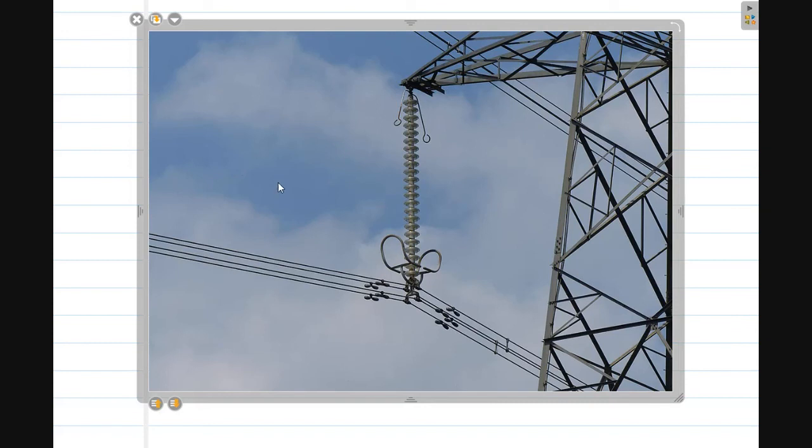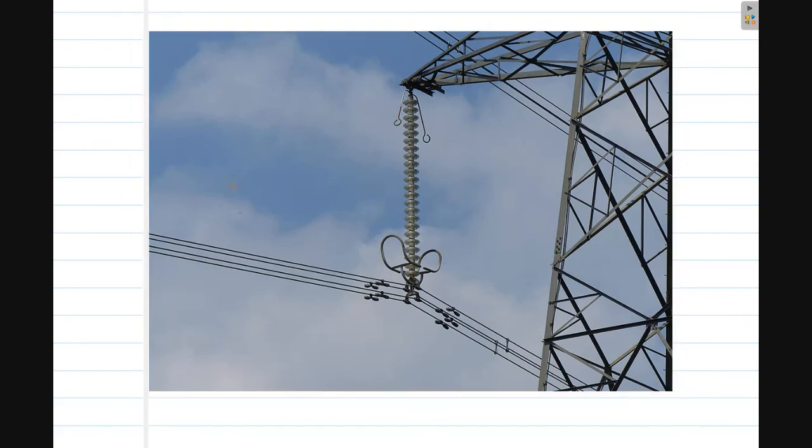The second application is in transmission lines. In transmission lines, there is also a problem that because of wind flowing across the wires, they tend to vibrate because of flutter and sometimes galloping. These are high frequency self-excited vibrations, so you can see small dumbbell-shaped masses attached.